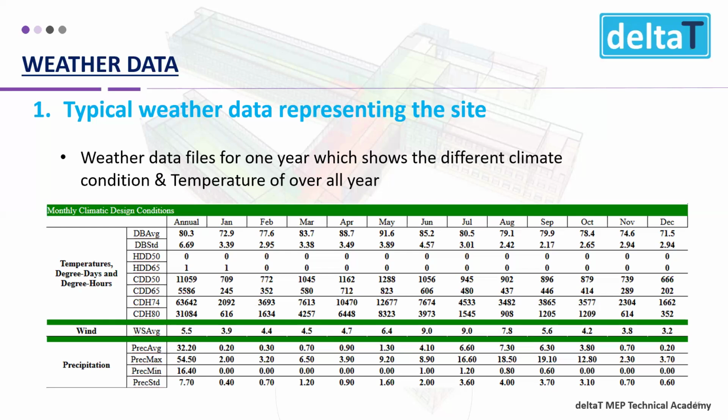Imagine outside temperature in Hyderabad goes up to 42, 46. Based on that peak temperature, which appears in April or May, we do the selection of air conditioning. But to know the power consumption in each month, we should know the temperature for each month. Like here you can see January to December, we have different temperatures. So this is what we go with here for weather data.